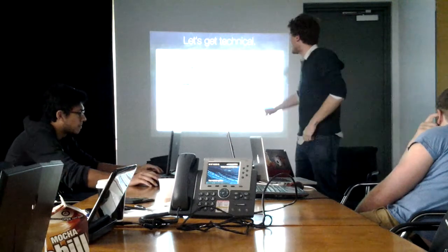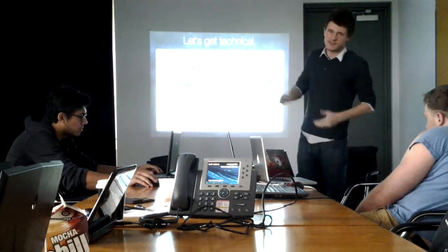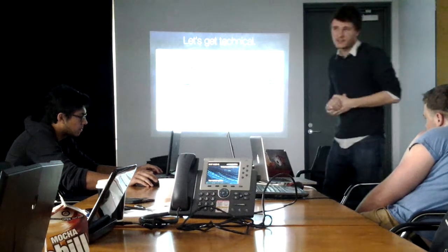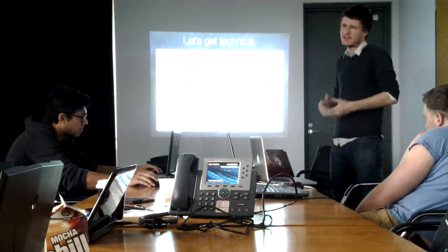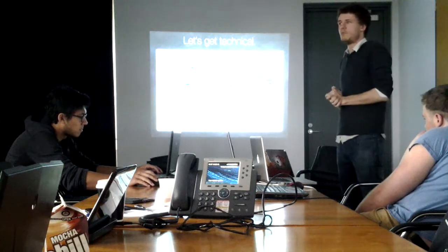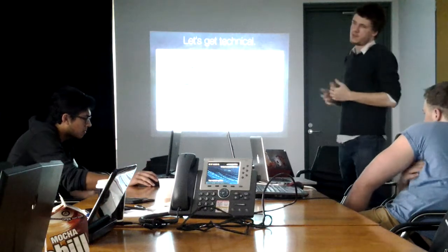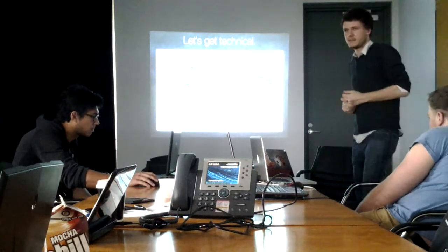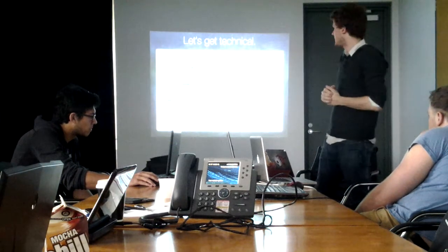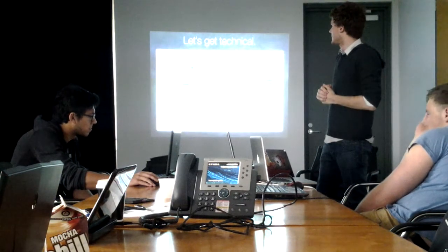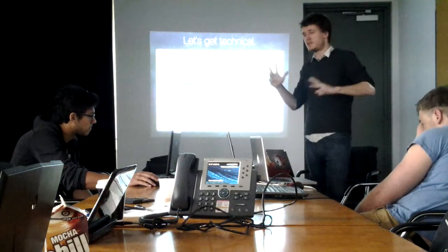So a little bit more on the WRF pre-processing system. It's made up of three main parts. You have your static data, which is essentially geological data, so mountains, heights, elevation, soil densities, all that sort of stuff. Stuff that basically doesn't really change in the sort of timescales that we're dealing with. Then you have your grid data, which is your initial atmospheric conditions, so things like temperature, pressure, water, humidity, all that sort of stuff. So GeoGrid takes your static geographical data and maps it onto your simulation domain, so where you're interested in simulating.